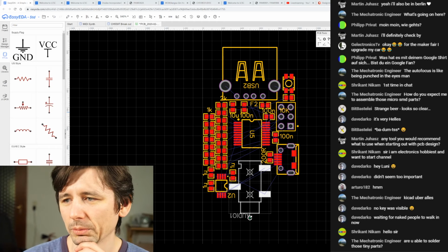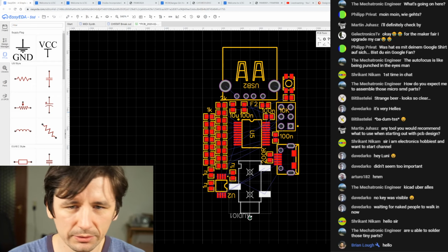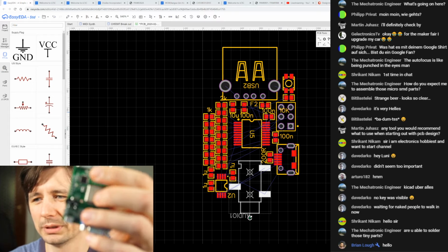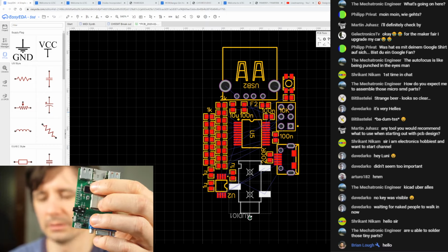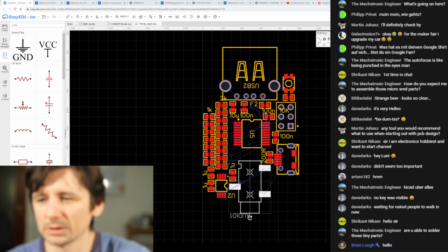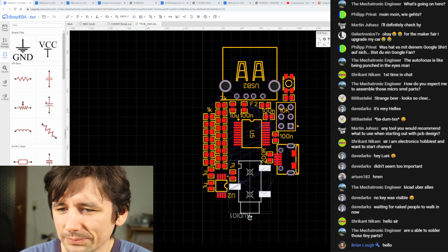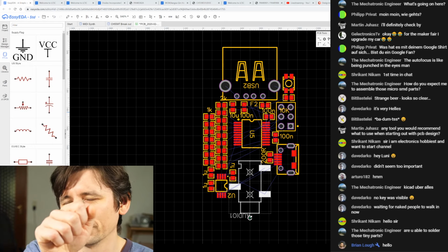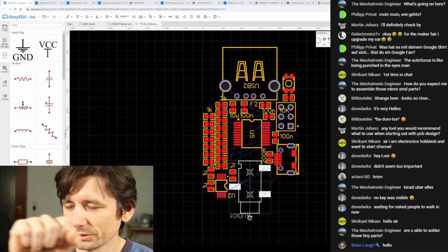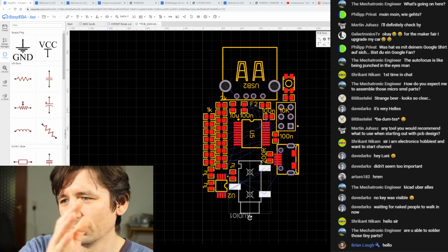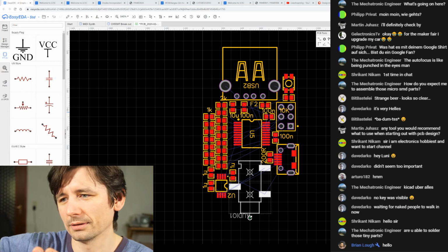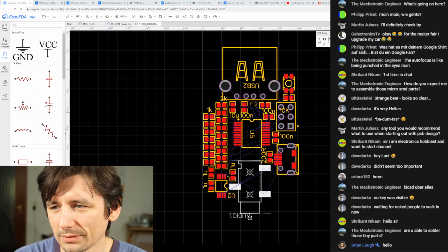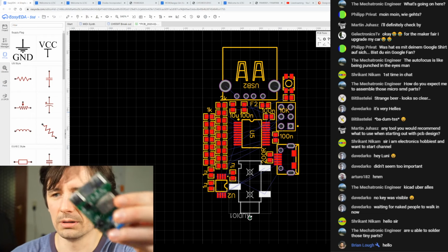Oh yeah, no worries. The parts are quite okay to solder. But the half millimeter pin pitch of the chips is the most difficult to solder, so I get some solder bridges there. But if you use some flux and move the soldering iron away from the chip, you will drag the solder bridges away, and they will stick to the tip, and you can clean the tip. So this is how I get rid of the solder bridges.